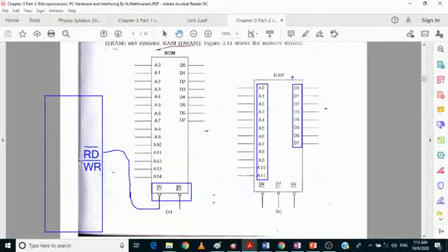Now when you study the RAM device, we are able to perform the read operation as well as the write operation. RAM is the temporary memory. As we have read-write operation possibilities, there are 2 control signals: one is the output enable signal, which is nothing but the read signal, and the other is the write enable signal, which is nothing but the write signal. As usual, the chip enable signal is there. It is connected again to one of the address decoder outputs, so that it maps this memory device into the memory space.